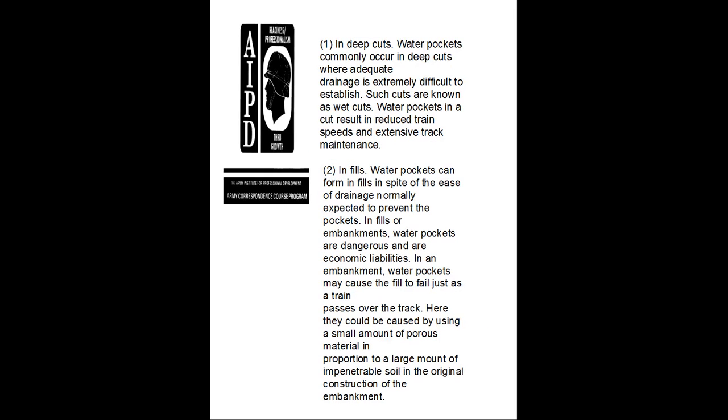Water pockets can present problems in deep cuts and fills, under heavy traffic, and in freezing weather. 1. Deep cuts. Water pockets commonly occur in deep cuts where adequate drainage is extremely difficult to establish. Such cuts are known as wet cuts. Water pockets can result in reduced train speeds and excessive track maintenance.